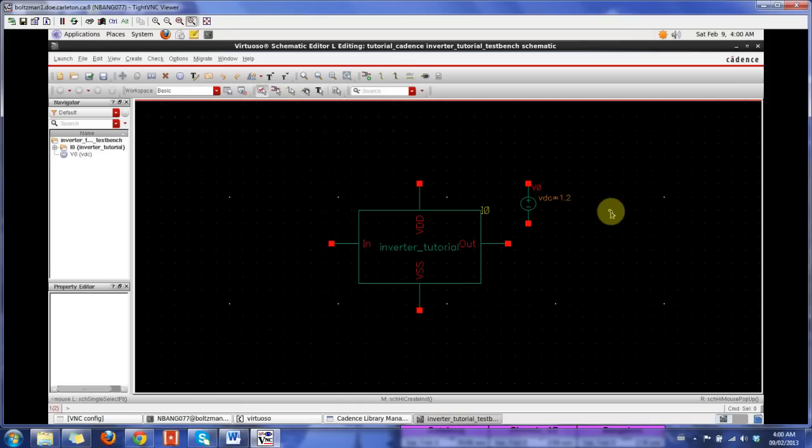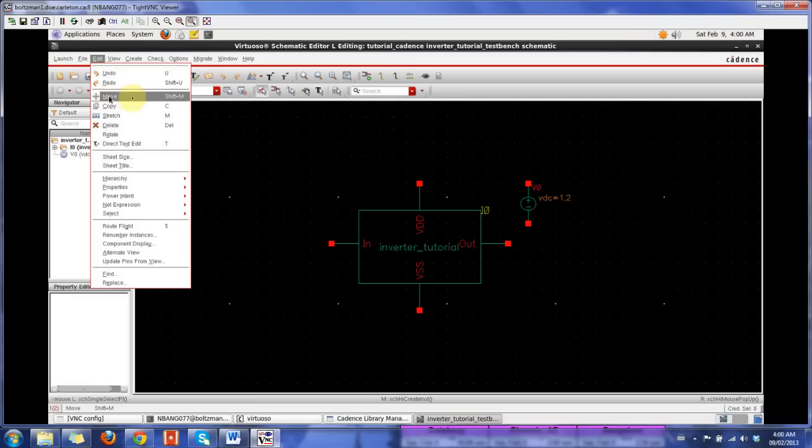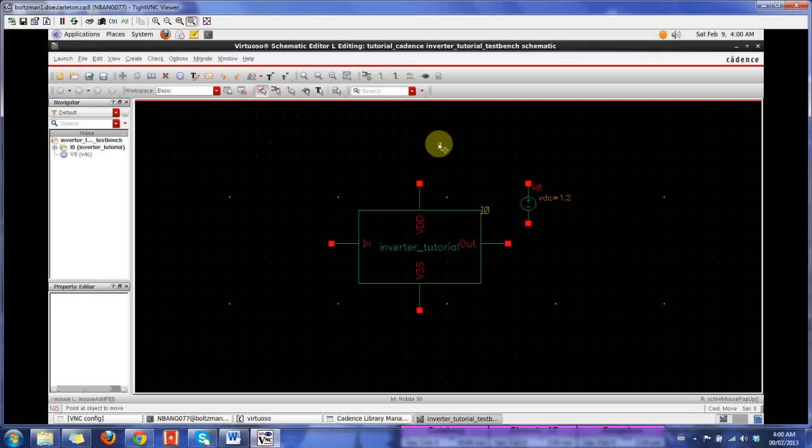Now it's common that people try to move things around for space. What you could do is move this DC source or any of these. I would go to Edit, Move, the bind key is Shift M. If I click on move, Cadence gives a command here, point at an object to move, and this is the command it's going to run. I'm going to click on this DC source to move it anywhere I want. I'm just going to space it out. There you go. Escape key.